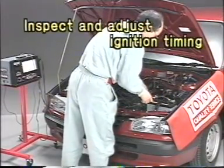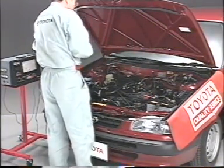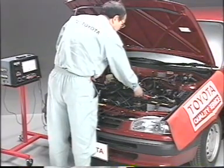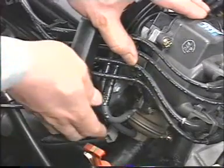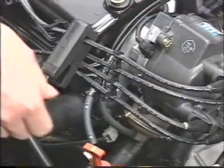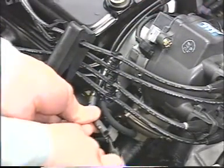Next, inspection of ignition timing. First, connect a tachometer and timing light. Disconnect the vacuum hose from the distributor subdiaphragm and plug the end of the hose. Then set the initial ignition timing.